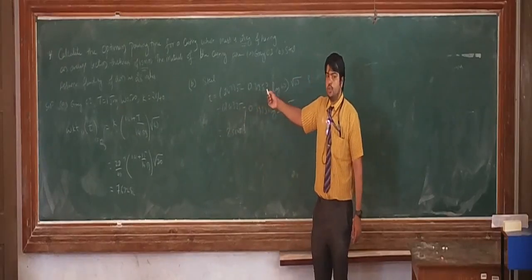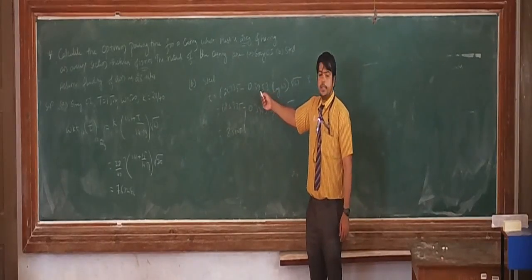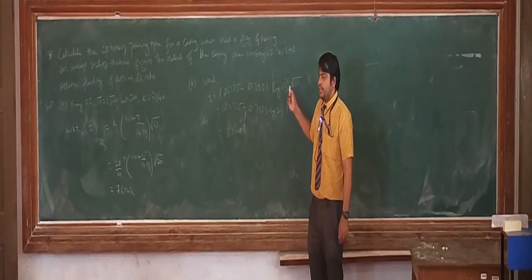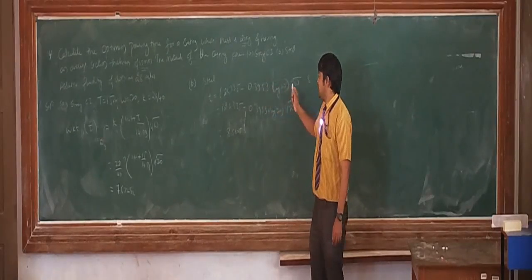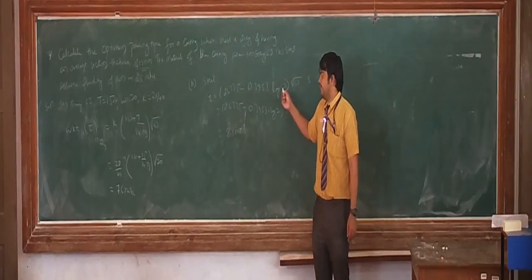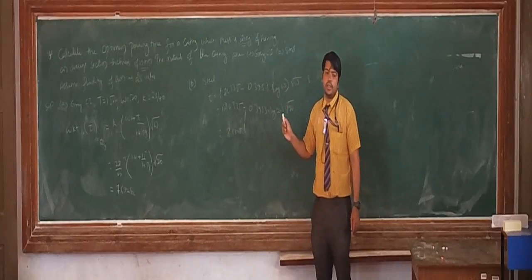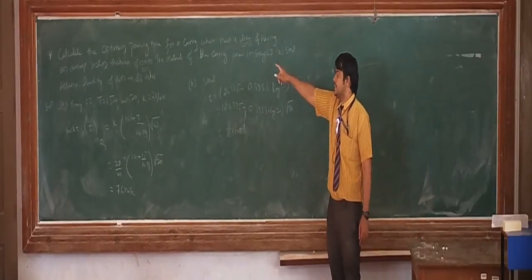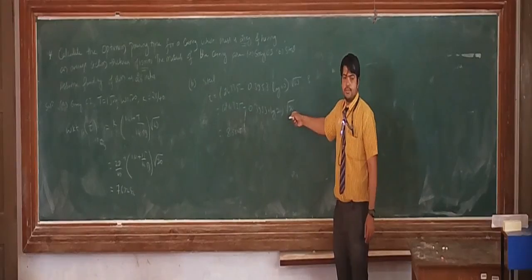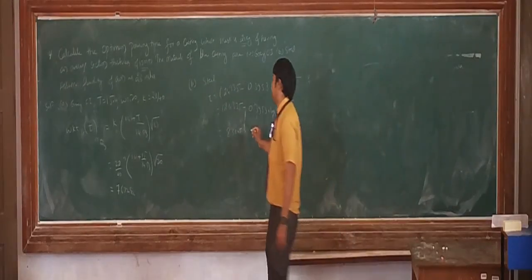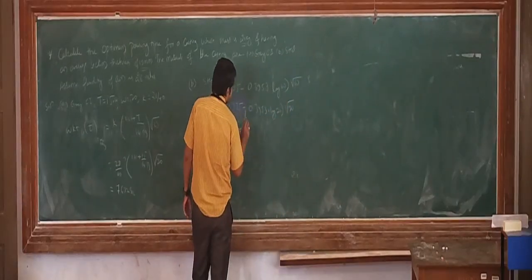Okay. Similarly, for steel, we have the formula for pouring time. T is equal to 2.4335 minus 0.3953 log W. The entire thing is multiplied by square root of weight of casting. So here, wherever the weight of casting is there, we are going to substitute the value of weight, that is 20 kgs. So once we substitute those values, we are going to get 8.58253 seconds.